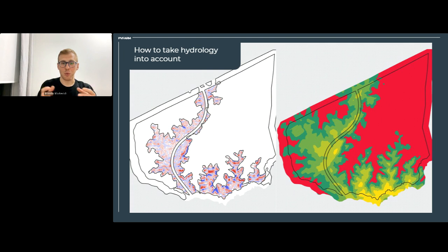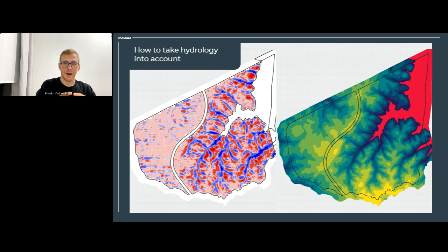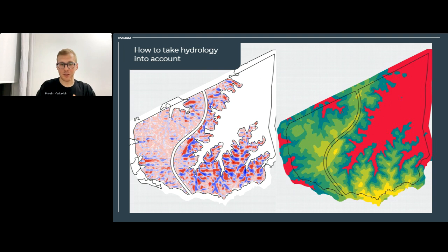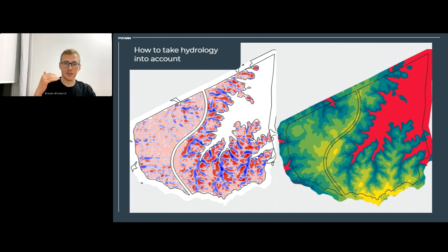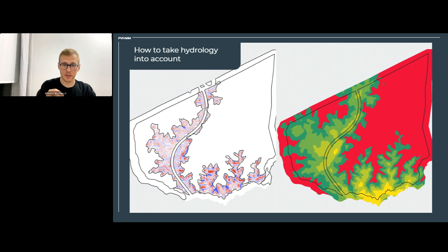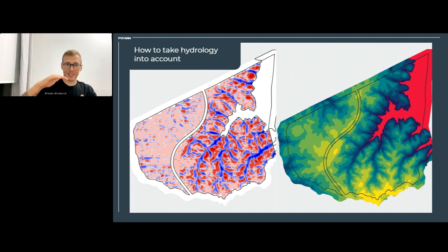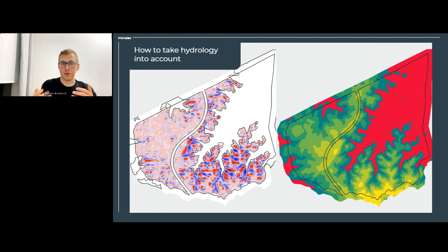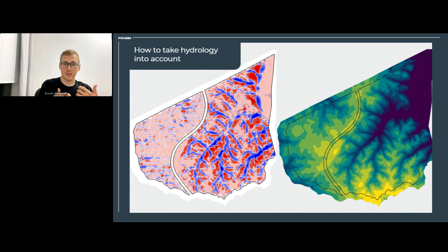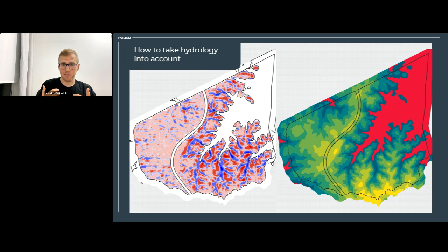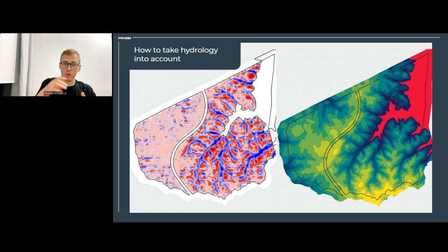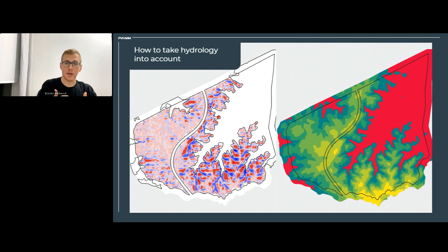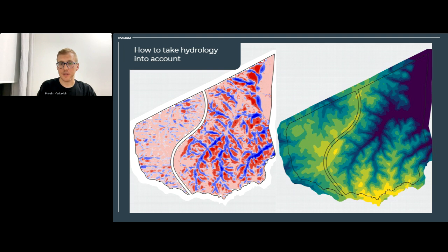So basically when you're working with the layouts, you can actually bring as many surfaces as you want, and based on specific parameters like elevation or based on slope, you can actually start creating boundaries. It's like cuts of the surface, right? And as you have boundaries, you can start avoiding those and run grading analysis in the areas outside of those boundaries, or you can start applying different grading strategies.